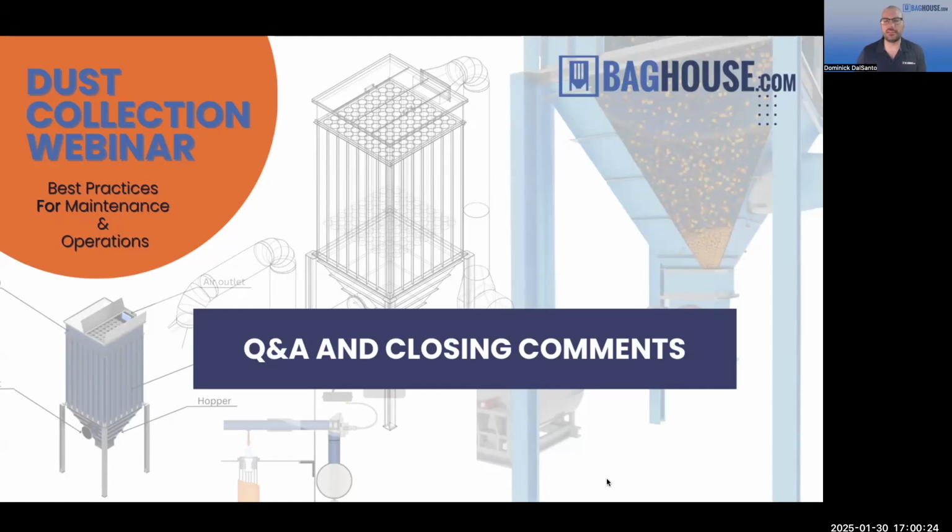What are some common things we see with the airlocks, the hoppers, and all of that kind of stuff that cause problems? So hopper flow problems are really common, and we can always spot them because you go out on site and you look at the hopper and it's all banged up. You can see where they've taken a rubber mallet or a hammer and banged on the side. Okay, there's a discharge issue that they're dealing with. A couple things it could have to do with the dust. If you have moisture in your dust and it sticks to the walls and bridges, that can be a problem. That should be addressed separately, but more specifically to the discharge equipment.